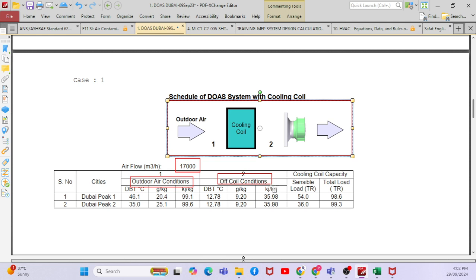That is why normally, whenever you go with the calculations, you will calculate based on 34, 32 and what supply temperature is required for the space. So that is the delta T, right? So 34, 32, and what you are going to achieve after the coil will be a low temperature, which is you will cool lower than 14.4 degrees Celsius. That 14.4 degrees Celsius is the maximum dew point temperature, right? So you are going to cool lower than that temperature. Clear, right? In that way, you can calculate the delta T.